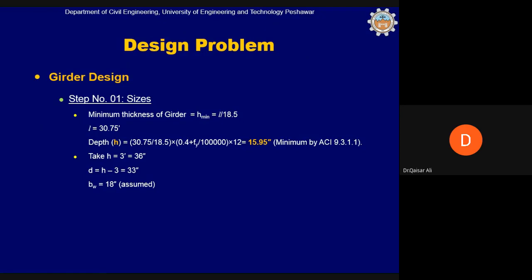It is obvious that delta will increase with the increase in length, but it will also increase with the increase in load, W. But in order to simplify the equation, the ACI code has omitted the load part and only included the length part. But there is a disadvantage to this simple equation, and the disadvantage is that it does not contain the load part.